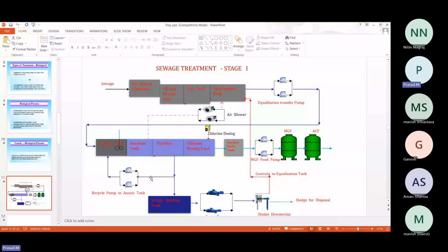Cell residence time is a term, because as a human being, when we are taking birth, we will die also after a certain period of time. Similarly, bacteria will also die, and that dead bacteria is nothing but waste. So that's why we are removing some sludge for wasting, and some sludge we recirculate, because some bacteria will be dead, some bacteria will be active.